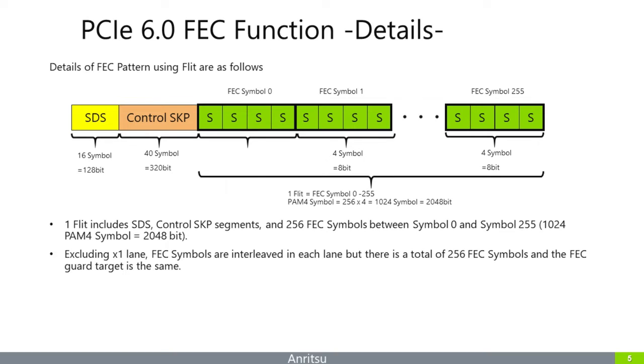One PAM4 symbol consists of 2 bits, which means one FEC symbol consists of 4 PAM4 symbols, that is 8 bits. So 1 byte is 1 FEC symbol.